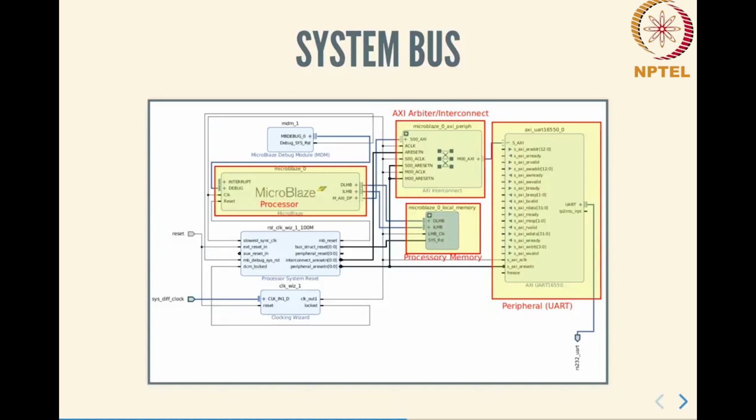alone. Similarly, we could also have a set of wires forming an address bus. Another set forms a data bus, typically 32 or 64 wires that are grouped together and called a data bus. And maybe some other wires that indicate whether or not a read or write operation is required from the memory, whether the address is valid, whether the data to be returned is valid, and so on. The combination of these groups of wires together is sometimes called a system bus.